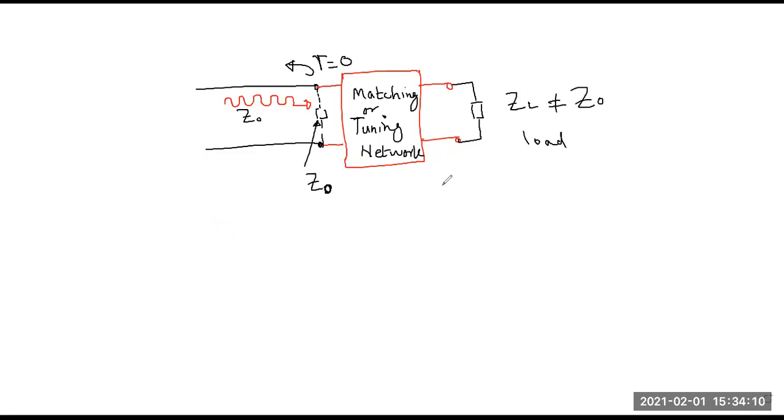So in order to design a matching circuit, we use some kind of circuit which converts, or transforms, or you can call it maps, load ZL to Z naught. And now we get this matched behavior. Okay. Now I was talking about whether it is possible that whenever you have this situation, you can always design a matching circuit to get this behavior. No, it is not possible.